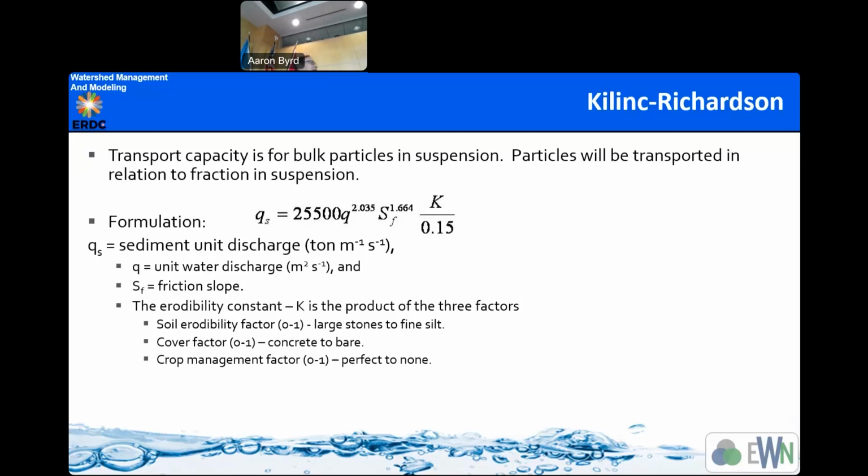But certain things, sometimes we define them like parameters. For example, the initial soil state, right? Initial condition. Many times we see, even in literature, it's a parameter. Actually, it's not. It's a state variable. That's the initial state variable. Just like critical shear stress, it's not a parameter. It's a value for a particular soil type.